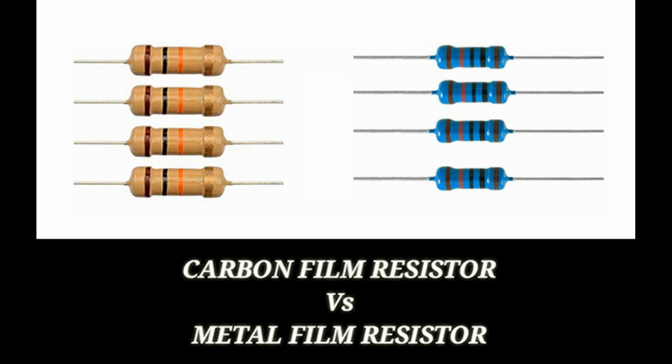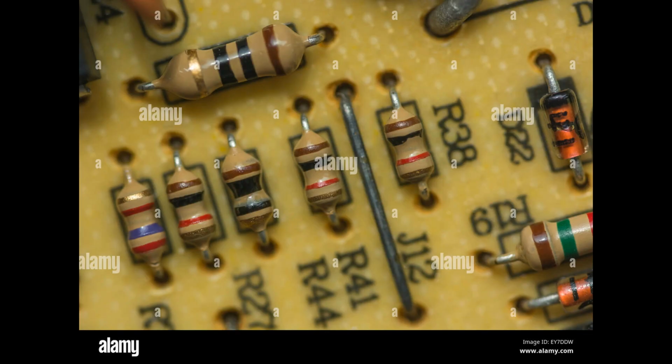A resistor can dissipate more power if subjected to higher voltages or currents, or if its resistance is lower. Examples: a 1/4 watt resistor is designed to safely dissipate up to 0.25 watts of power. A 1 watt resistor can safely handle up to 1 watt of power. A 5 watt resistor is capable of dissipating up to 5 watts of power. High power resistors, such as those used in power electronics, can have power ratings of several tens or even hundreds